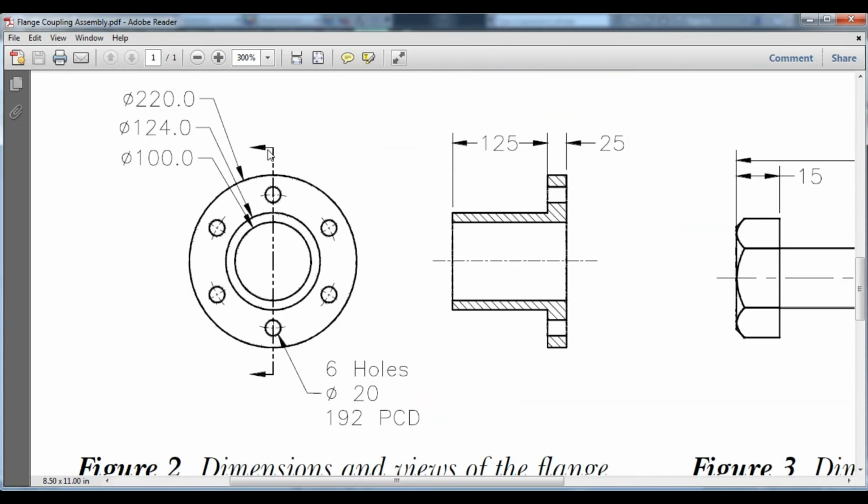See here, they have given the cut section like this, and in the cut section the side view is like this. So it requires one axis and this profile, correct? In this profile, this is called the hatching. Actually, this is a complete hatching. Why is this hole not drawn? Because this section will be solid, so we should not create this hole part.